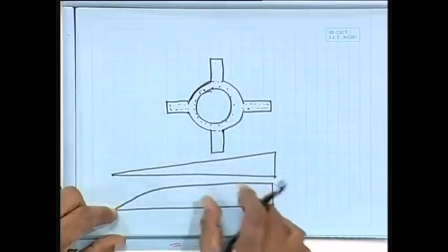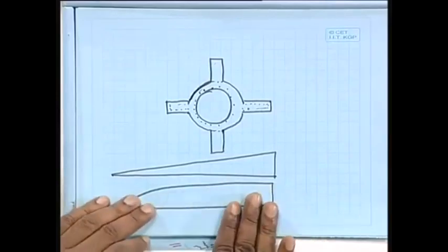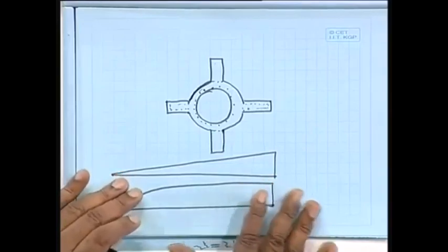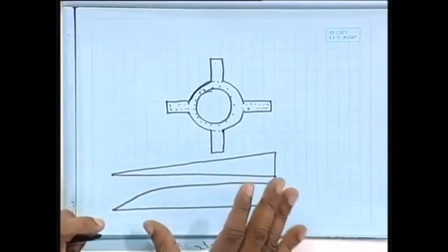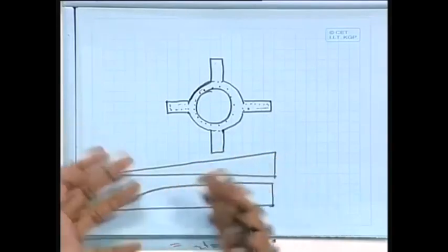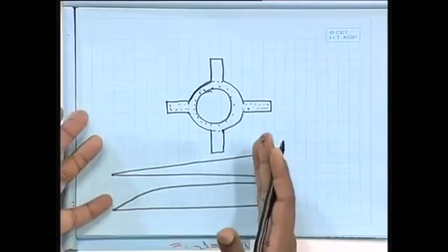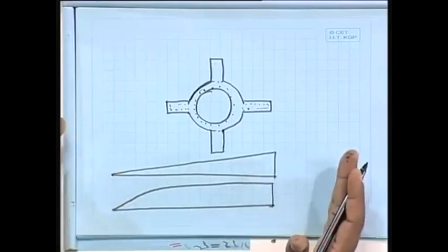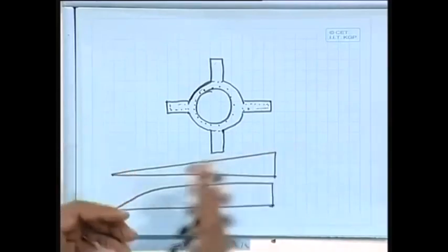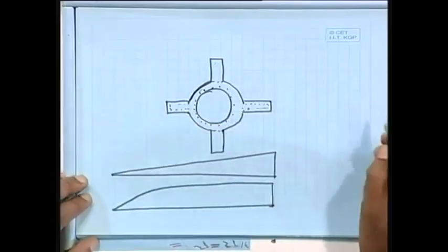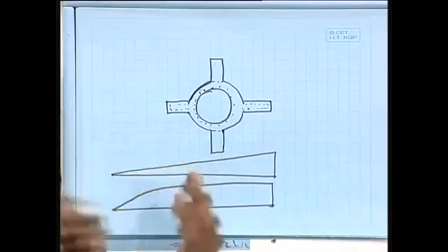So wherever you have the stress diagram, if you can understand the stress diagram and strain diagram, say in the limit state method of concrete design, immediately you can find out the moment capacity and axial load capacity, as we have always found. That's what we are doing here, and it is very simple. The 0.0035 and 0.002 are the different strains, and on the basis of that you can find out. So what I mean to say is that apparently it may look very complicated, but it's not so.